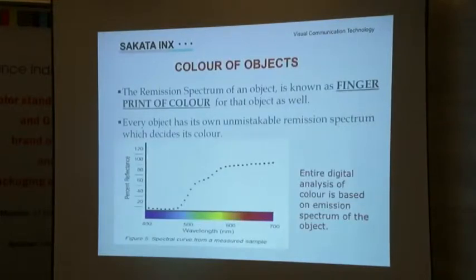Now, from the design to get the final output, there are many processes. So color will not change if the process does not change, but if the process changes, then color will change. So there is always a delta. That's what somebody had been discussing, LSD, light standard dark. So to accommodate the deviation of processes, we come to certain approval norms, that the color will be approved if it is lying between this LSD.